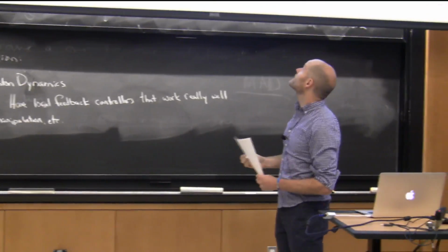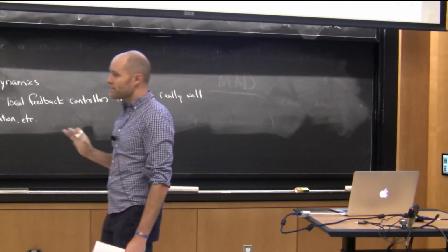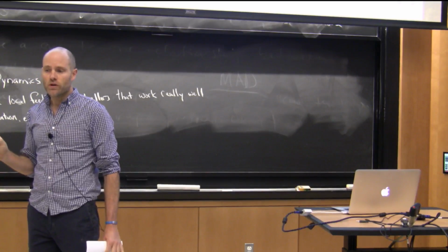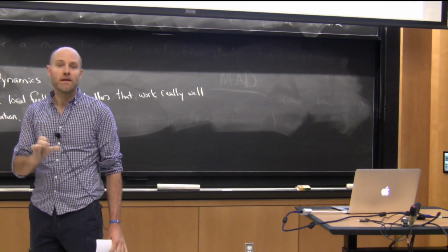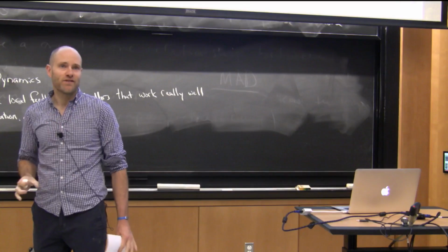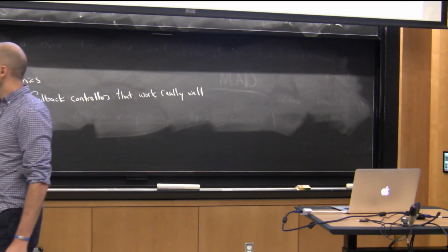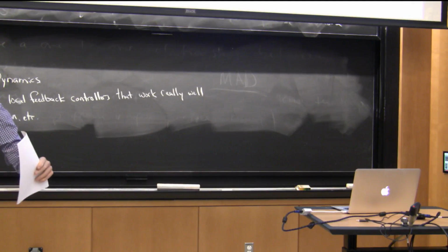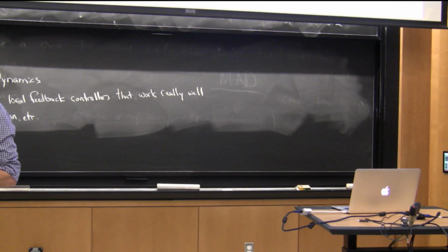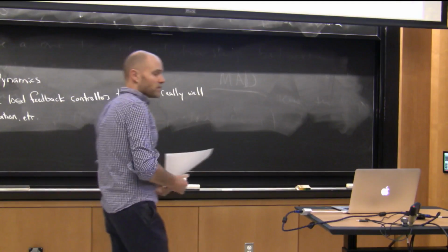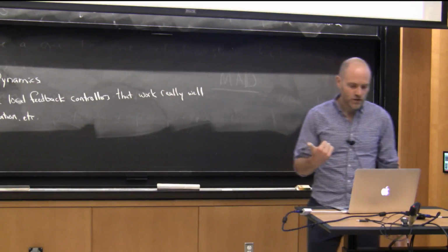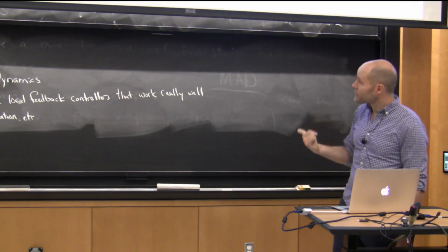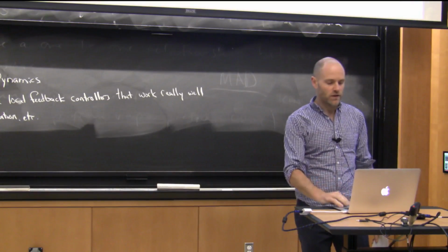Now, how do you put it all together? So the second part that I was sort of missing from the Burridge work was a recipe for filling out space. But RRT roughly gives us that recipe, right? So the idea of having space filling by sampling, rejection sampling and then growing out a tree fits pretty nicely if you're able to make these funnels using trajectory optimization and local feedback stabilization. So here's sort of the proposal for combining motion planning with sums of squares and trajectory optimization for the pendulum.